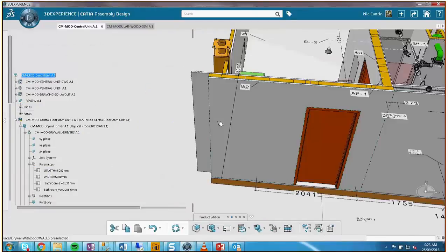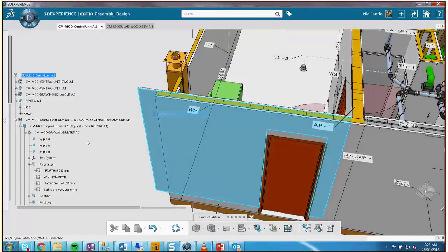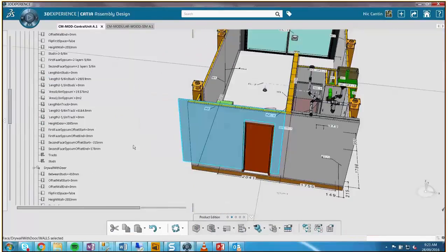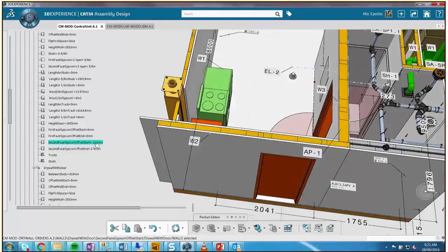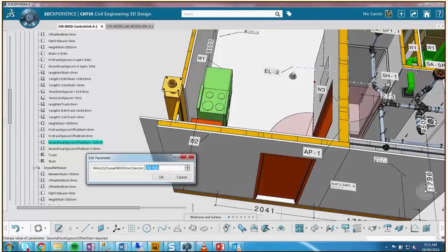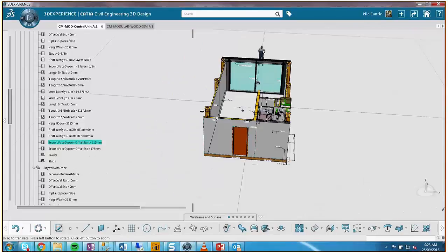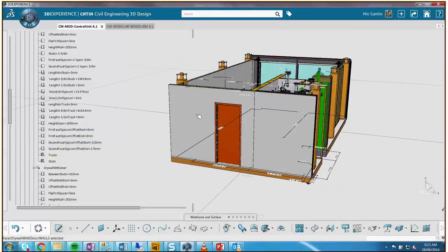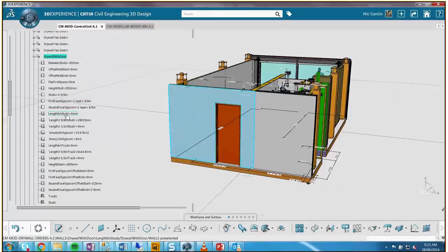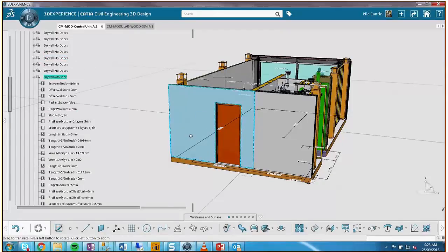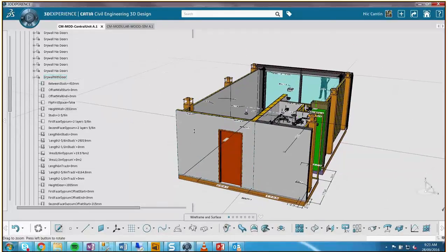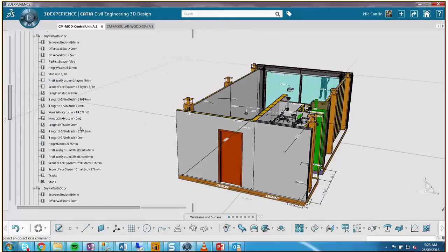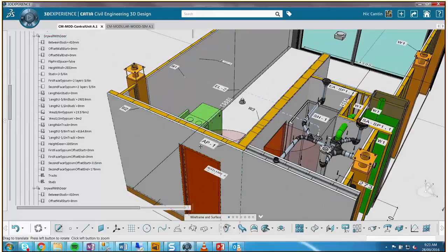As you can tell, there are a few issues with the directionality of the line. Sometimes the direction of the line will move, and because of that, our offset of the gypsum there got messed up, so I have to reverse that. There are a few limitations with the tool, but overall it's much better than actually modeling the wall itself, or having just an extruded pad representation instead. So it's still a lot better in most cases.